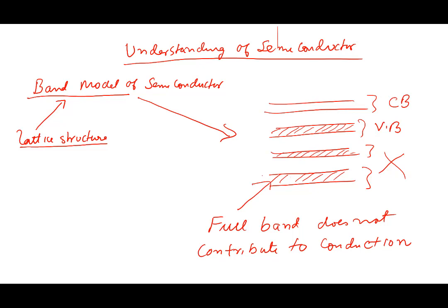And we'll not go into the details. If you look into the band here, for every electron that is moving right, there's an electron moving left, so they all cancel each other. It's not that the electrons are not moving in these bands. The electrons are moving, but they all cancel each other. So the focus is on the valence band and the conduction band, because at typical room temperature, the valence band gets a little bit empty, and you start getting electrons in the conduction band.